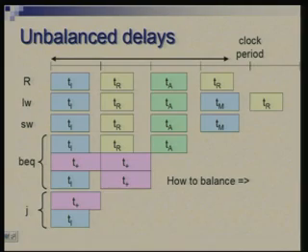So what can be done in such a case? We have to do something so that there is balance. What we are doing in a clock cycle should be uniformly the same. That means we identify the activity to be performed within a clock cycle which is generally balanced. It should not happen that, for example, in this clock cycle we are doing very little and wasting a lot of time, whereas this cycle here is packed. That is the imbalance.